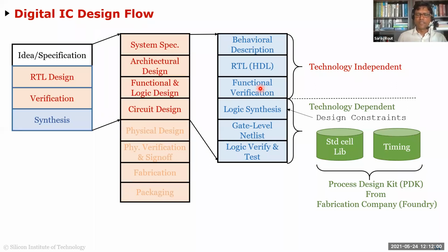When you go to semi-custom, a lot of these processes are automated. So you use tools going from RTL design to gate level netlist. You use tools from gate level to do placement. You use tools to route them. You do clock tree synthesis.